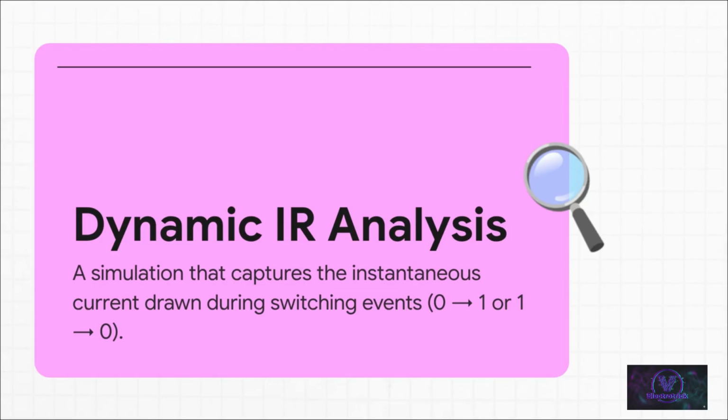At its heart, dynamic IR analysis is this incredibly powerful simulation. It's not looking at averages anymore. No, it models the chip's behavior at the exact moment a transistor flips from a 0 to a 1 or a 1 to a 0. It's all about capturing the real instantaneous burst of current drawn during those split-second changes.